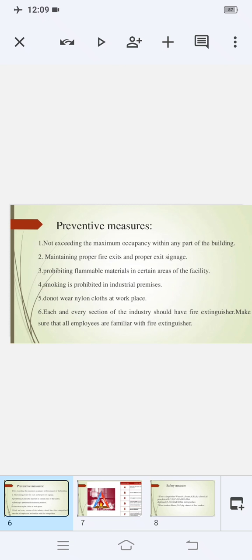When combustible construction is involved, firewall cutoffs should be provided. These cutoffs should be standard firewalls of at least 13 inches of brick or equal construction, with all door openings properly protected with single or double automatic fire doors. In construction, what else can we include? Exit points. Exit points of adequate capacity should be provided so as to enable employees to reach a place of safety outside the building in case of fire. Every factory or working space should have at least 2 exit points from each story.